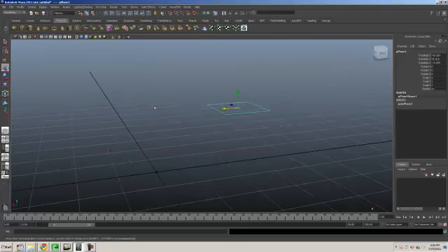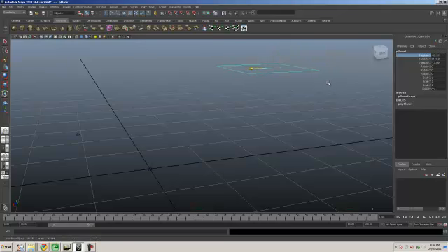If I haven't mentioned it clearly before, with this object, the plane, selected, if I click on translate X and middle mouse button drag, you see only the X axis is going to be changing value. Middle mouse button dragging from left to right in the viewport is precise, is what you should do. You're going to be moving the object front and back in its X axis, the same way in Z axis. That's another way of being precise. You see what I did there? How the Z axis gets highlighted?